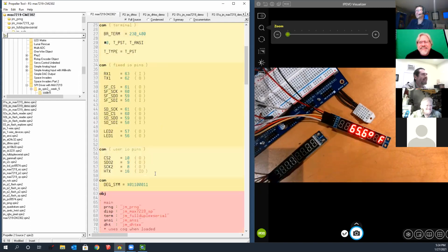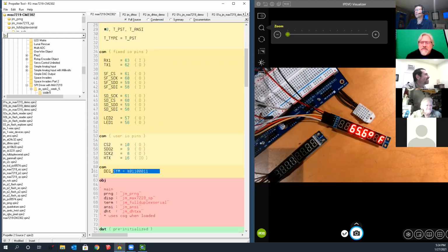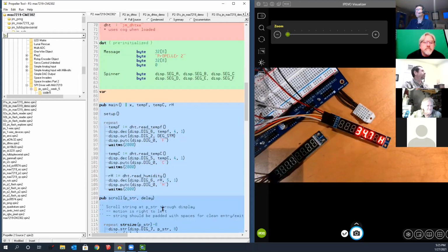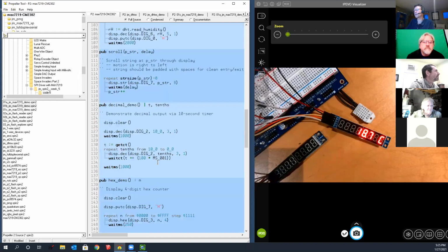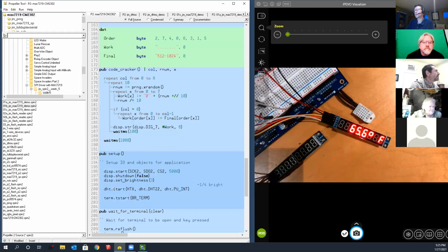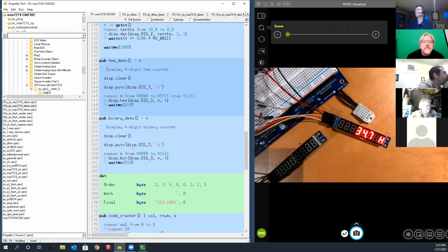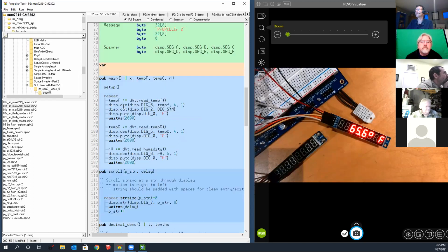So I added the sensor here on pin 16, and then John made the degree symbol. I put that in, and all I had to do was start up the humidity and temperature object, which is down here in the setup. And John can tell me if I did all this in the proper way or not, but I started it, so now it's running, and all those values are available anytime I want them, so I can just retrieve them in this main loop.